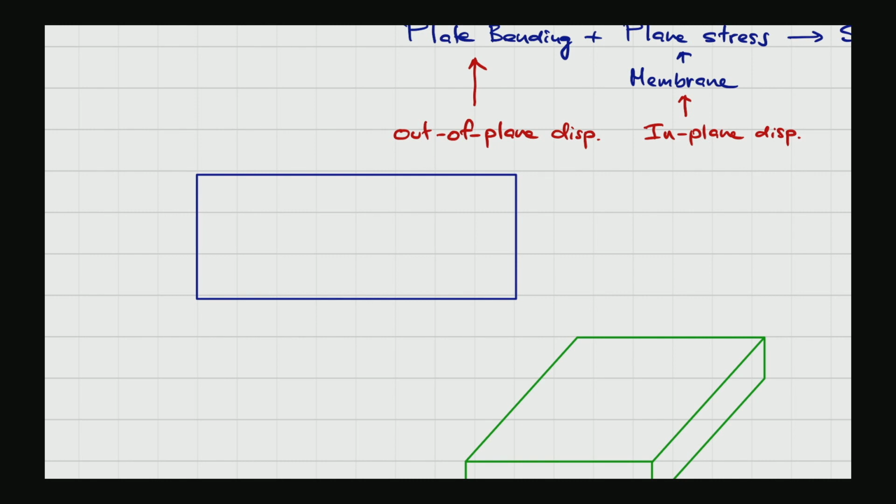The strain distribution is actually coming from the beam behavior under flexure, and then the shear component was later on incorporated. But the pattern of the shear is not the same as the case where you have a structure of which the thickness is very large, like the pile cap.